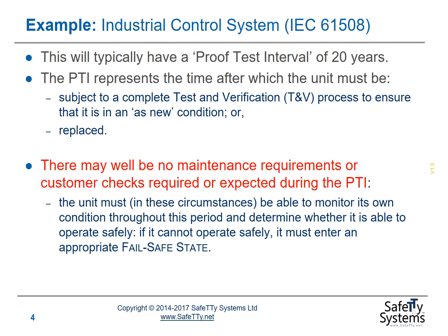So this means that we may have a SIL3 piece of equipment that's performing self-tests over a 20-year period, and that there is no other maintenance performed on the system. Ensuring that your system can operate safely over such an extended period is a non-trivial process.